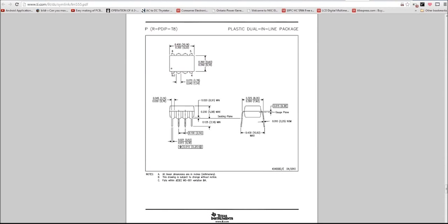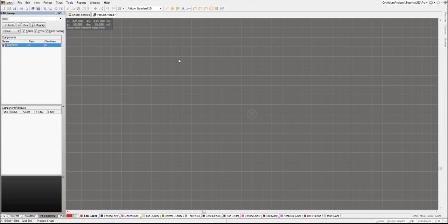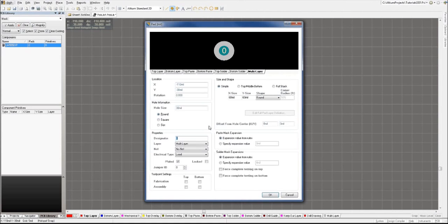As you can see, you have your pins 1 through 4 and then 5 through 8. Let's get started with the first row of pads in Altium Designer. For that, you can either click this button, place pad, or you can press P twice. As you can see, you get this very nice little round pad, and to change its settings you press tab on your keyboard. Right now it's actually the perfect size, as I've corrected some of the details for this pad.